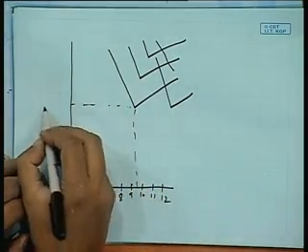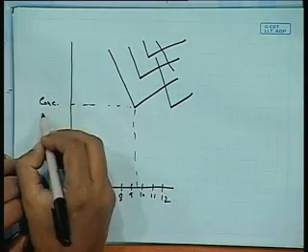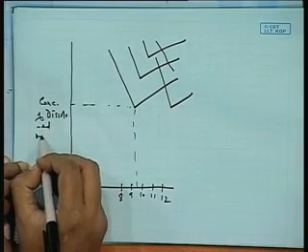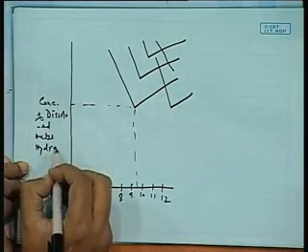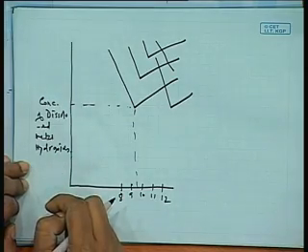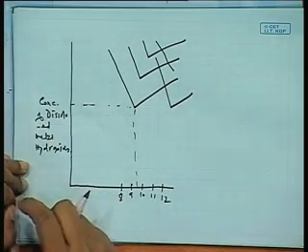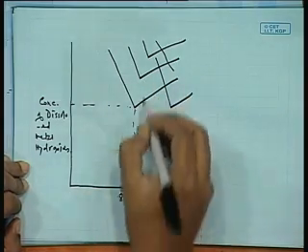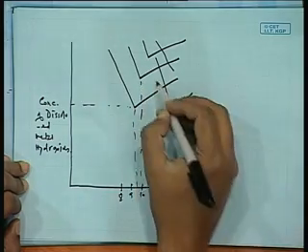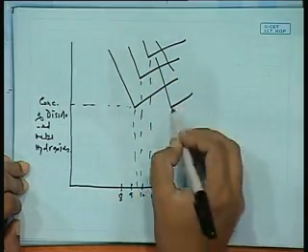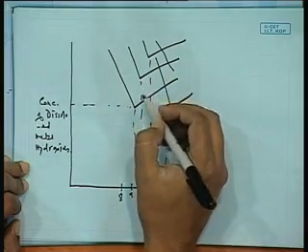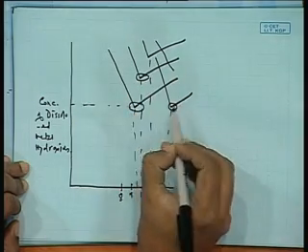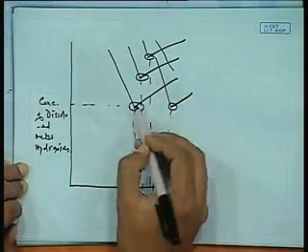This is the concentration of dissolved metal hydroxides. If you manipulate the pH, all of these can be precipitated selectively. If you want to do it selectively, you can do so by targeting the minimum solubility zone.